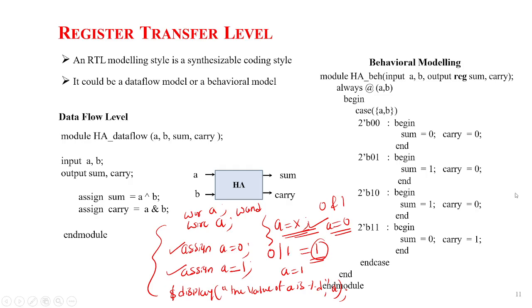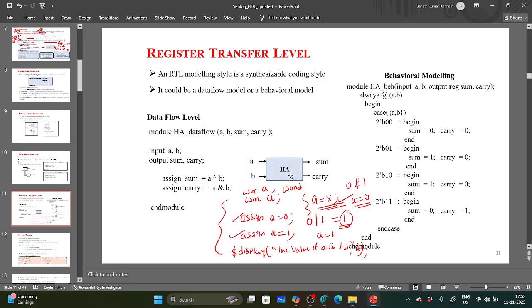Is it synthesizable, or is it just for the test bench? This is for testing only. It is not synthesizable. When you want it to be synthesizable, you need to write either in data flow modeling or behavioral modeling, that is RTL code, and only then is it synthesizable. I will show you how it is synthesizable. Let me show one program.